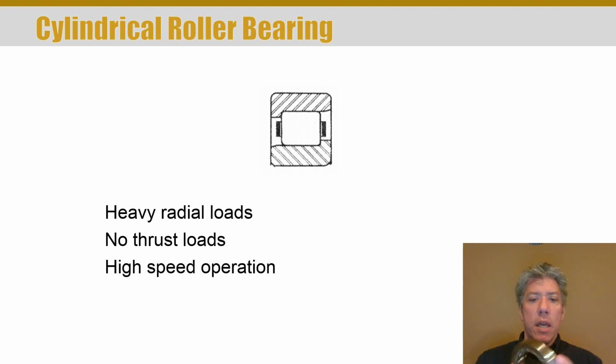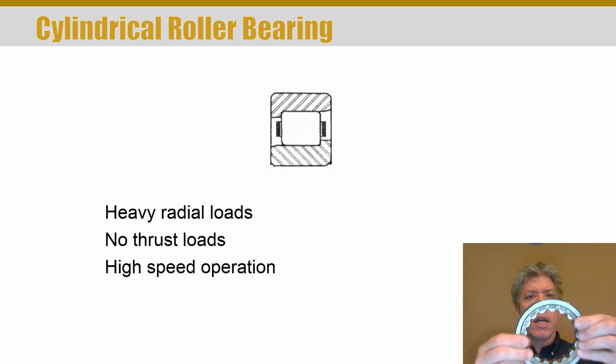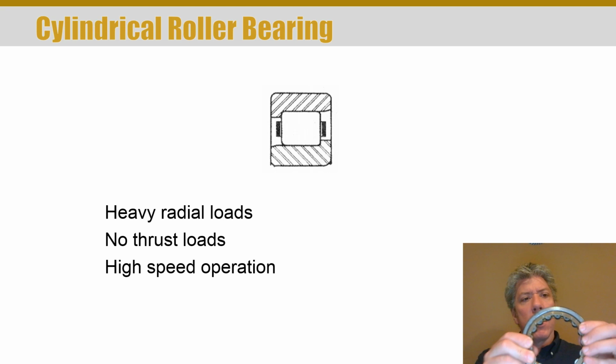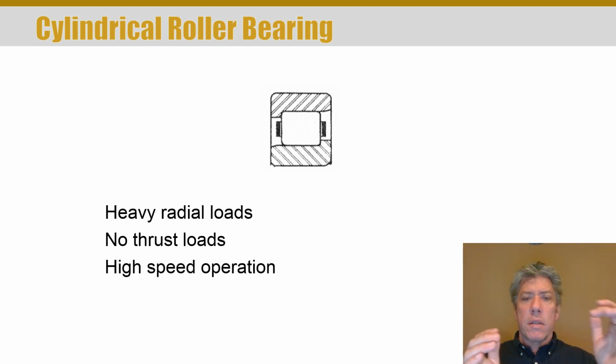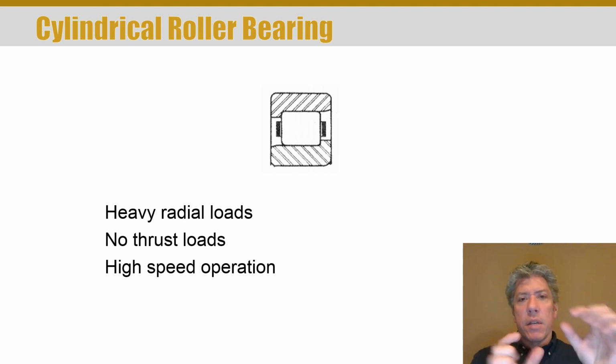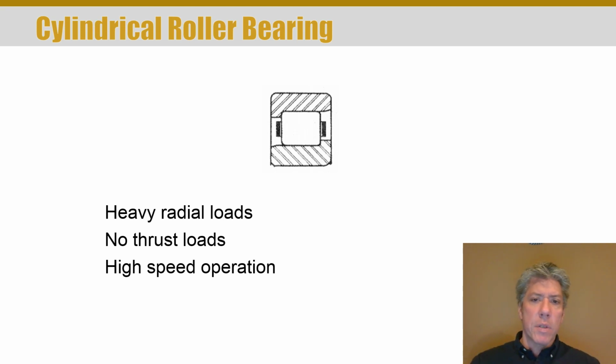Now, I don't know how they've done it, but they've somehow captured the rolling elements in the outer housing. Probably it's some type of engagement between the cage and the outer race. Anyway, you can see in the schematic of half of the bearing that the outer race and the inner race wrap around the elements just a little bit.